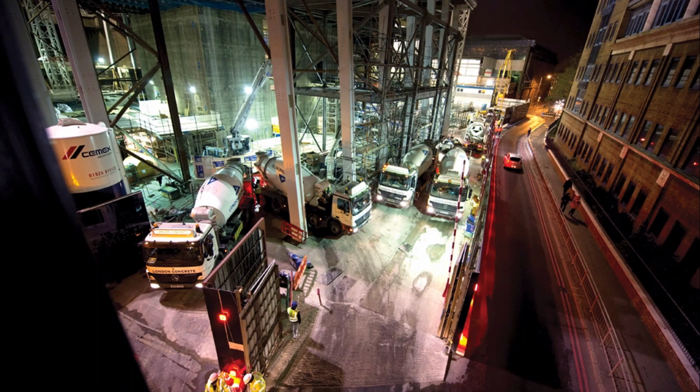For the equal hardening of the concrete, they had to pour concrete continuously. For this huge raft concrete scale, 4 pumps and 44 wagons at peak were used, and 36-hour continuous pouring was done, which is the amount of concrete used daily for a general building. During this, 700 concrete mixers were used. Next, piles.